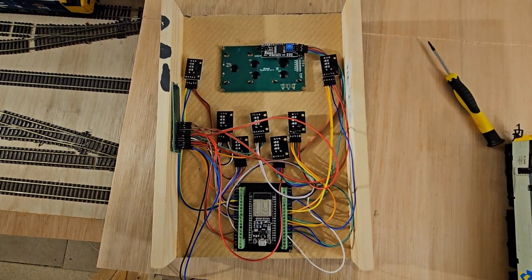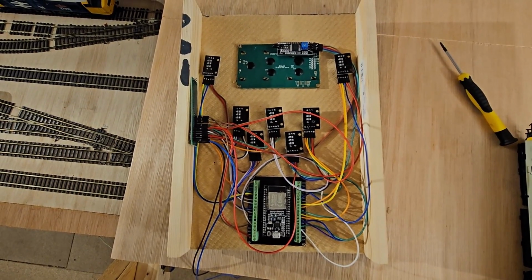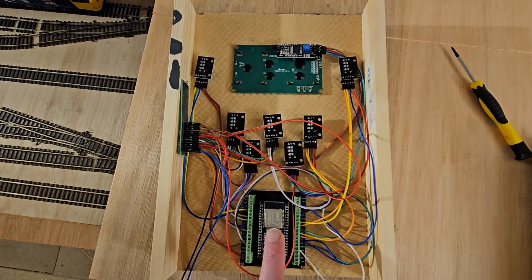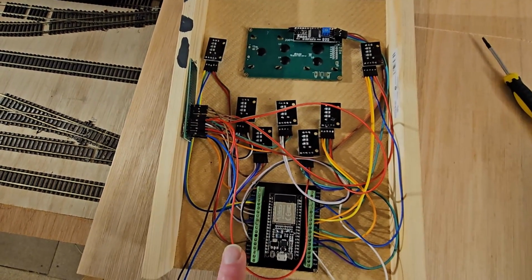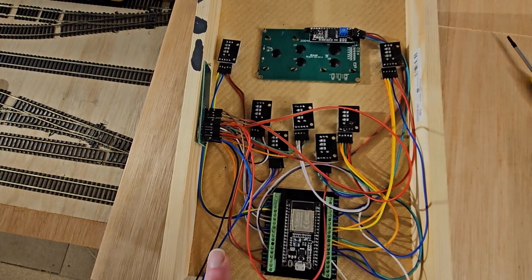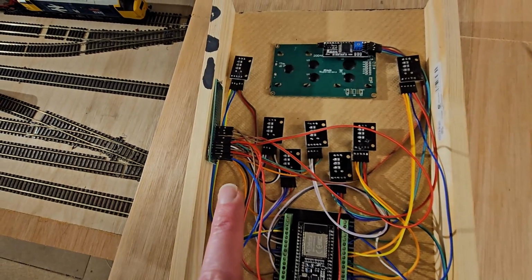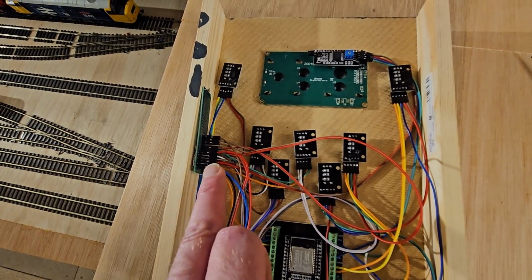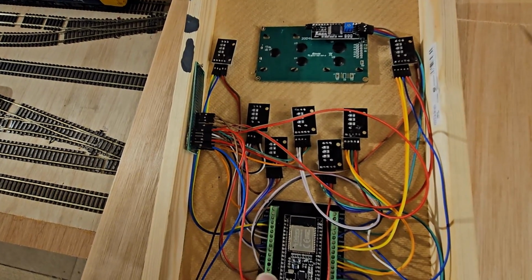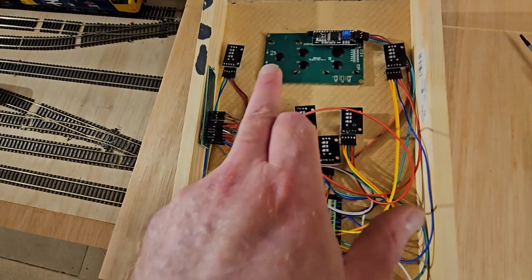Here's box version 2 then, hopefully wired up and ready to go. I've got the ESP in its little harness there, screen fixed up there, all the knobs fixed on. There's a 5-volt power supply just coming from down below to there, which is going into here, into the shared ground, into the 5-volt. The 5-volt then comes out and powers both the ESP and the screen.